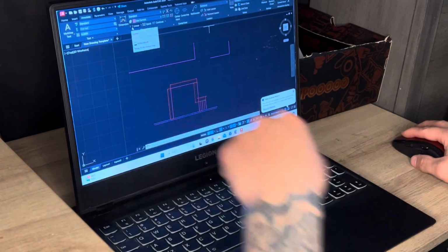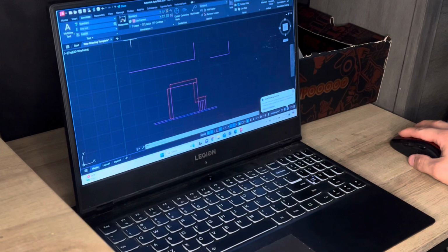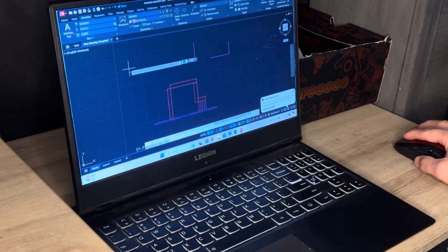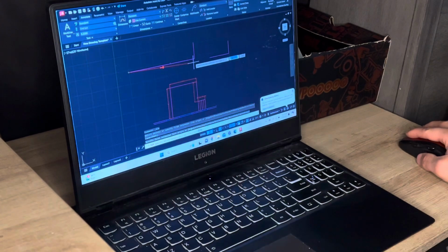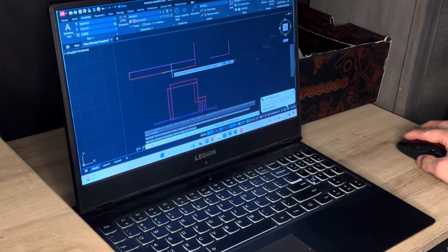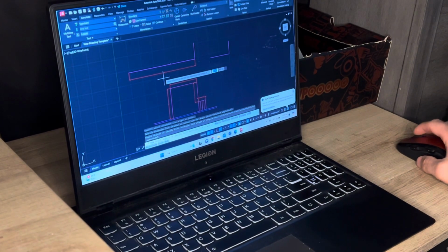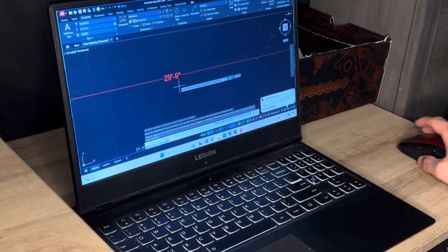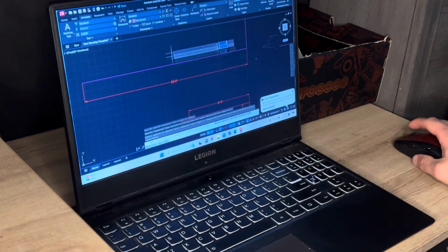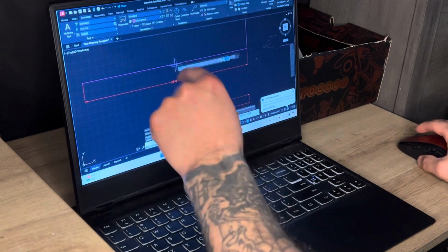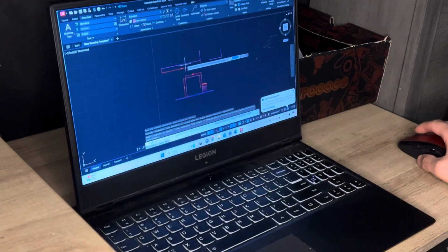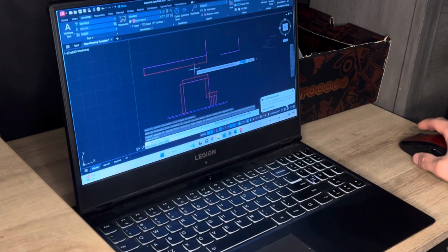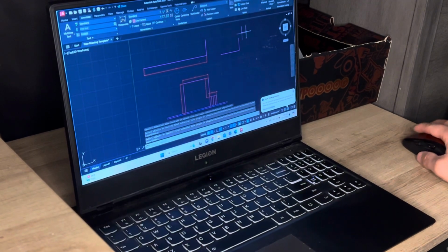When you do a dimension, for example, if I click this and I wanted to dimension what this was from here to here, then I'd click the 2 points. But right now that's kind of hard to see unless I zoom in, right? So I can go in here and I can alter this to read out bigger, so I could actually read it when I'm zoomed out here, right?